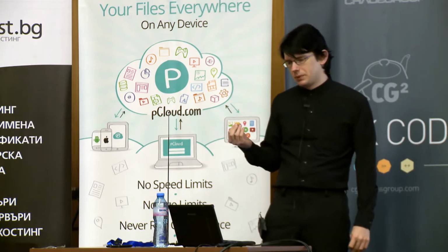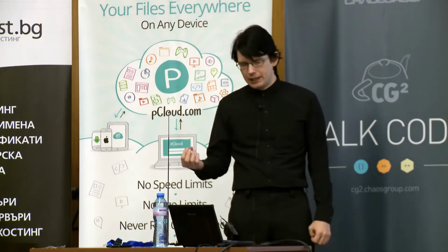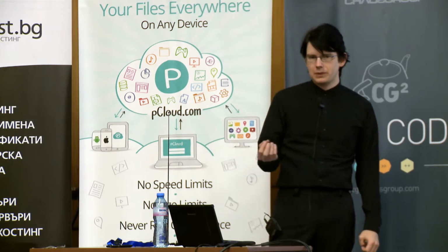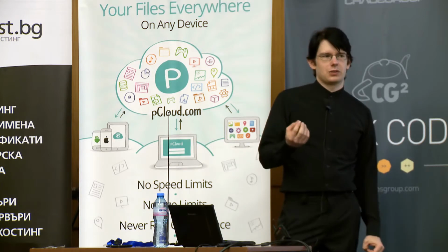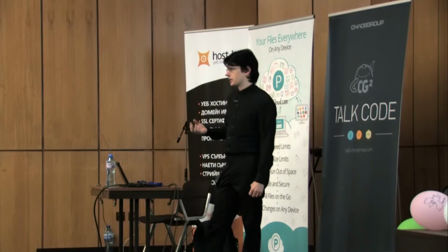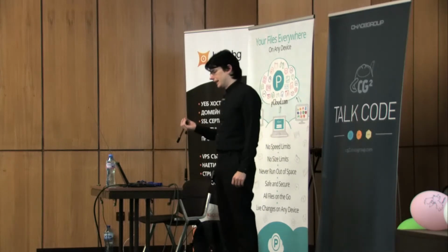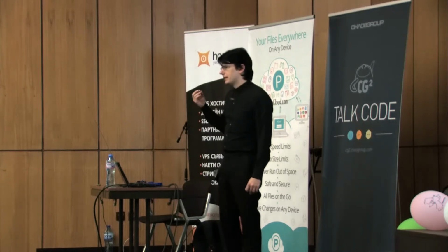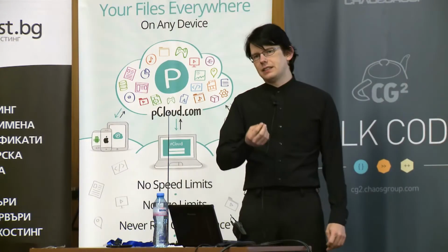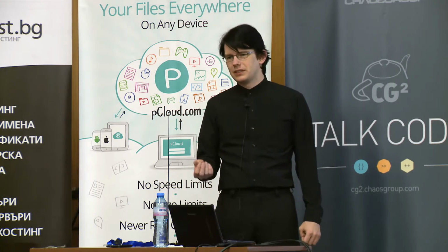which is a single chip receiver for digital broadcast TV. They built this chip with the intention of enabling people to build small USB dongles which you can use to receive digital TV, like DVB-T broadcasts, which are, at least all over Europe and in other regions now, the common form of terrestrial television broadcasting. This chip normally integrates the entire receiver and the demodulation for the respective digital TV standard, and all you get is an MPEG-2 transport stream over USB into your PC.